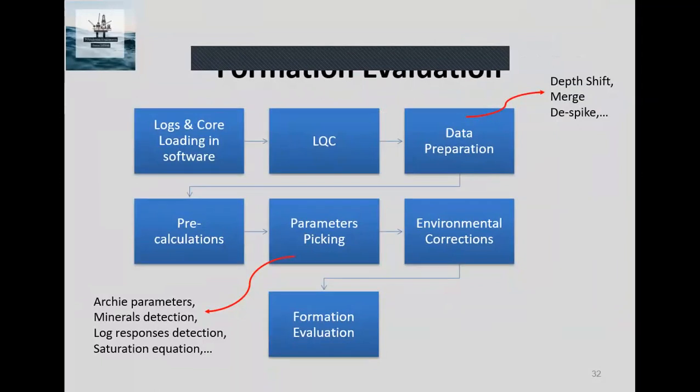QC of the loaded data, the preparation of the logs for entering the calculations, including the depth shifting, the merging, the necessary editing, and then entering the stage of pre-calculations, and after that determining the basic parameters needed for the evaluation, and then performing the necessary environmental corrections on the logs.